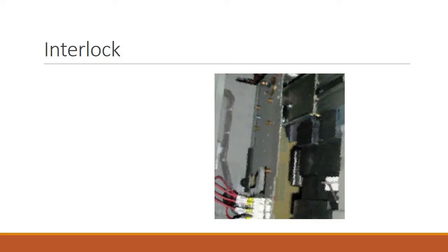It is feasible to guarantee that earth switches are closed only after the isolator has been opened using the same method. 2 locks with the same key combinations and a single key are utilized in this situation.